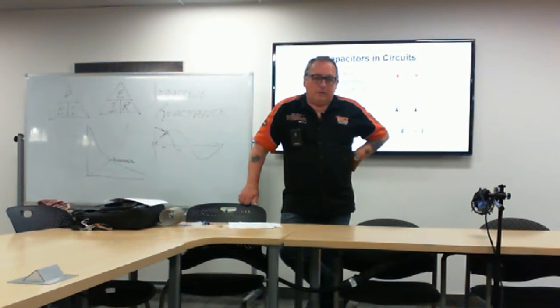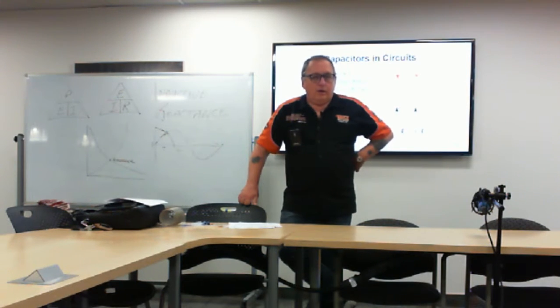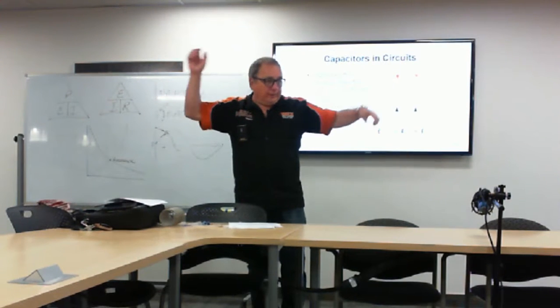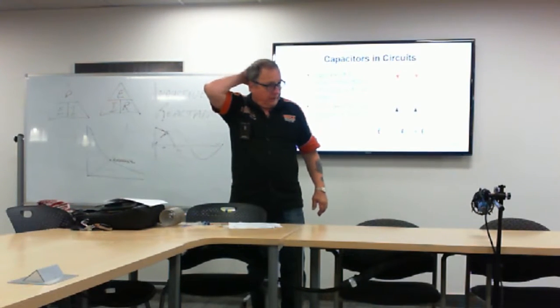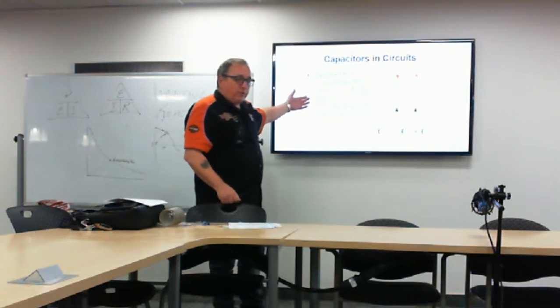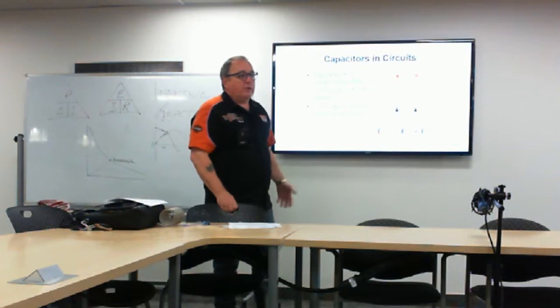But in our field, in ham radio, our output impedance is 50 ohms. You still can use the dipole antenna, which has a theoretical 300 ohm impedance. So we have to match that. And once again, we use a matching transformer, which is just a pair of inductors.